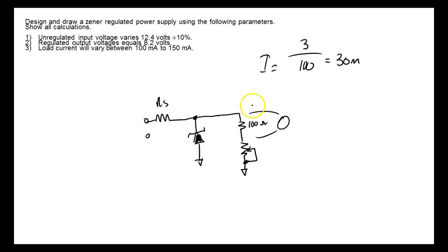And what you're going to do is you're going to measure the voltage across here, across the entire load, right? Does that make sense? To see what percentage your regulation is. So you know the Zener is not going to regulate perfectly, right? You understand that? So what we're going to do is we're going to go from full load to no load. We'll get our output voltage. So your Zener is going to have a Zener voltage, and we have what we call percent regulation. So your Zener voltage is what you want, right? You understand that? And then we'll come over here and we'll just subtract.